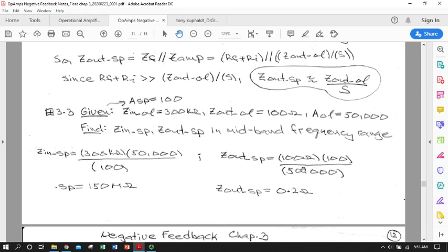So, easy peasy calculations. You can see we went to some amount of trouble going through some KVLs and some real basic DC circuit models to derive the relationships between beta and our open loop op-amp properties and our closed loop properties. And having done that, again, caution, the series parallel negative feedback configuration is one of the four, but it's a popular one. It's the one you'll probably see the most. But nonetheless, as long as you're sure that you have that configuration, you can just use these formulas that you just derived within their limits.